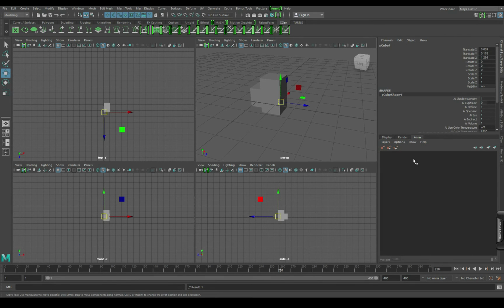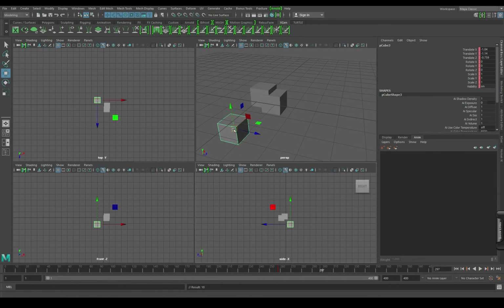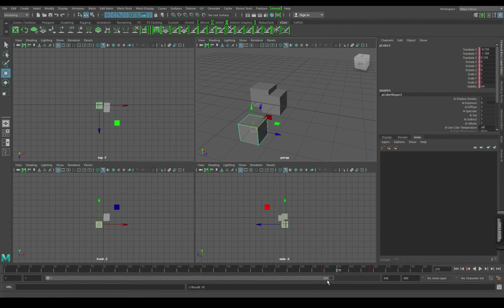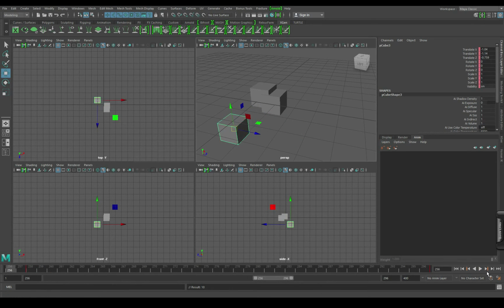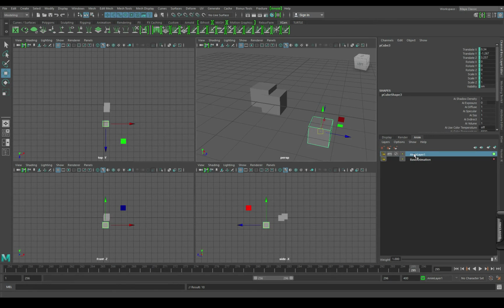And then your animation, you can animate with layers, which is amazing. It's incredible. So if I've got this little cube and I keyframe it quick and I move it a little bit forward, keyframe it quick, I've got this thing doing that. Remember this whole thing where I can grab this and take it down to there. Now I've only got the selected, see that? Now I've just got those selected frames. Boom. Okay, and the beauty of this is if I've got that selected, I create a new layer. Now I've got another animation layer on top of that, so I can start keying that one totally separate to the last one.